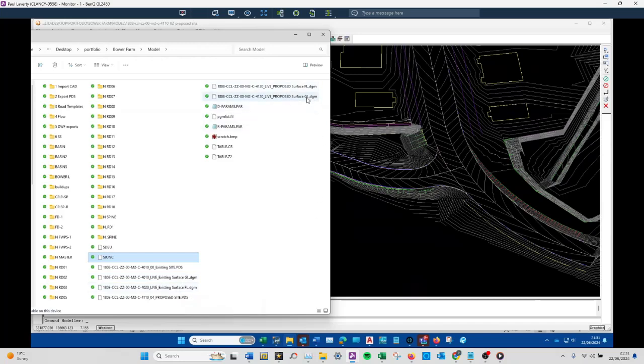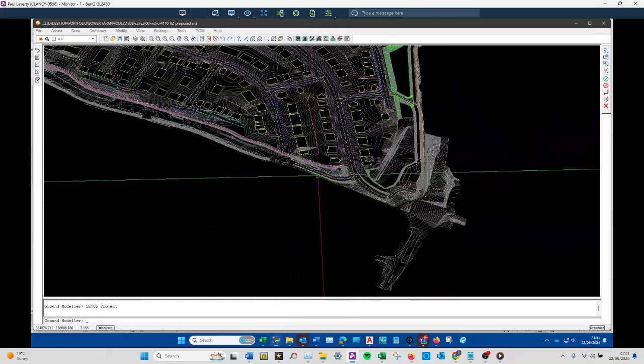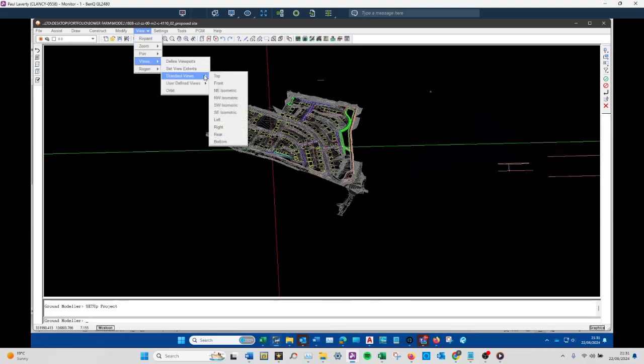And I have two of them. I have one that ends in GL, which is ground level, and FL, which is formation level. And that simply is the level of the ground once you clear out all the stuff. So you clear out all the existing concrete, clear out all the paved asphalt roads, surface materials, you clear out all the paving slabs, whatever. That's the ground level you have left over.